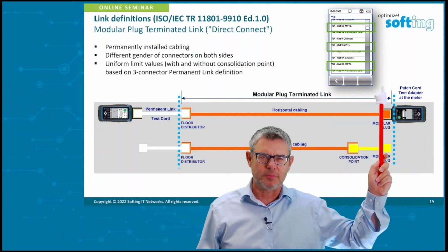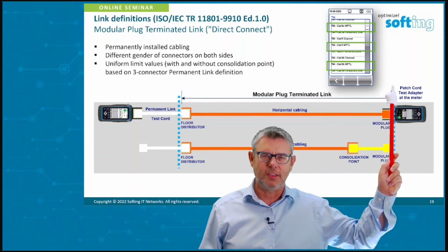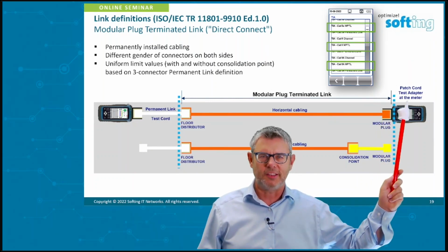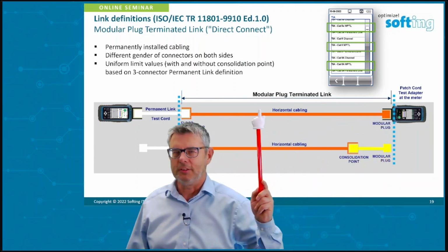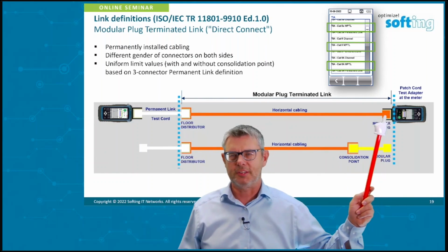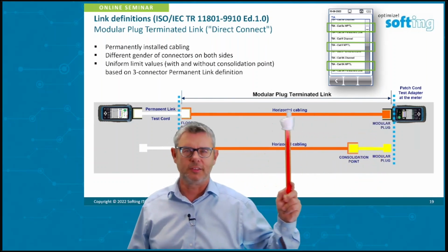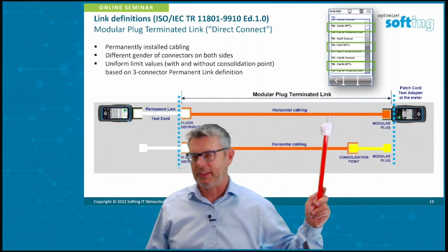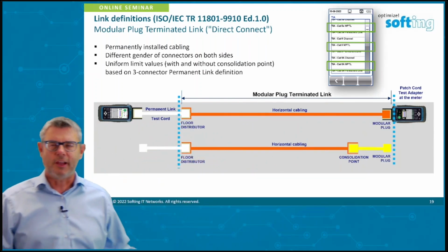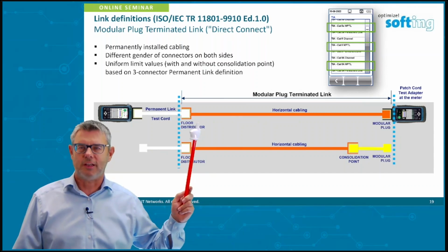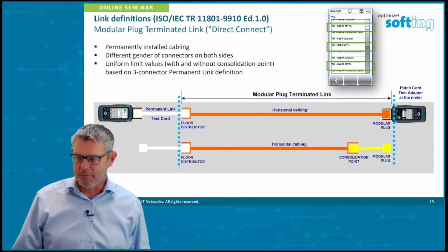And these adapters make sure that the reference plane is here. So this is a valid and proper measurement of an MPTL link, okay? Not using any other adapters or combinations of channel and whatever supporting cables and various things which have been used in the past. So this is now specialized and standardized how to do proper MPTL measurements.